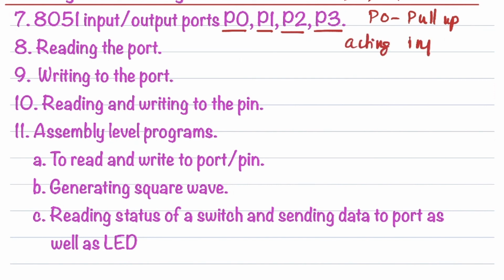To configure any port as an input port, we need to write 1 to the port pin, write high to the pin. To configure it as an output port, we need to write 0 to the pin or the port.